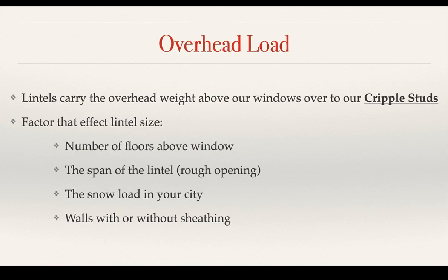So of course lintels are those beams above our windows that help distribute the weight from overhead to the sides onto our cripple studs or our trimmer studs and prevent our windows from just being crushed or preventing our doors from not being able to open because they're getting crushed as well.